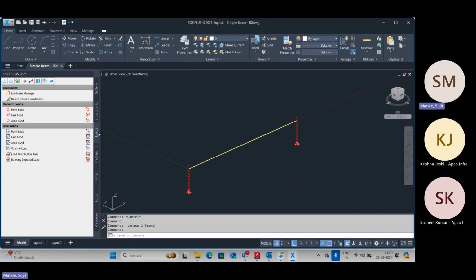So instead, what we do is we go for our combinations, okay, wherein our combinations will be LC1 into factor 1.5 plus LC2 into factor 1.35, 1.7, whatever your factors are. But if you go to the code, in the code, it is defined as per your actions. For example, it says dead weights or variable loads, or it says SIDLs.